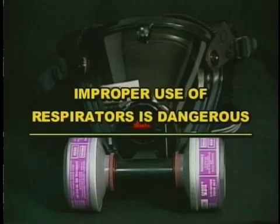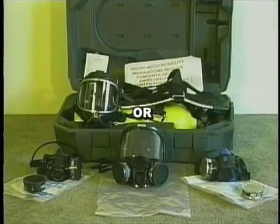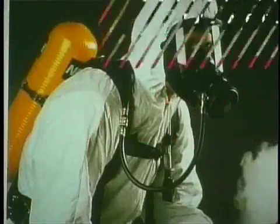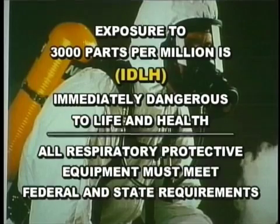Improper use of respirators is dangerous. Such equipment should only be used if the employer has a written program that takes into account workplace conditions, requirements for worker training, fit testing, selection of respiratory equipment, and medical exams. Where the potential exists for exposure over 0.1 part per million, use an approved supplied air respirator or approved self-contained breathing apparatus with full face piece. Exposure to 3,000 parts per million is IDLH, or immediately dangerous to life and health. All respirator protective equipment must meet federal and state requirements.